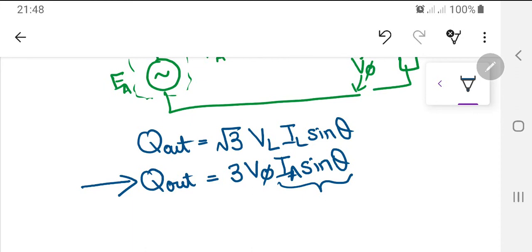They can just flow, because we know reactive power flows from the source towards the load. This means the power just flows from your home or your device, which is an inductive load, towards your grid station where the capacitors are attached. If it had to flow towards Tarbela and Mangla or any other powerhouse, maybe 1000 or 2000 kilometers away, then it would be an extraordinary current flowing through the transmission lines. And we know if more current flows through the transmission lines, you are going to have more I²R losses, and certainly more heating, more line losses also.